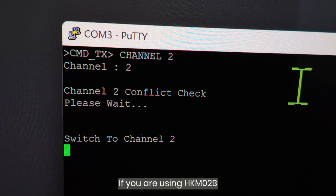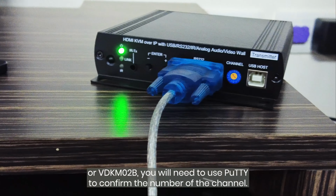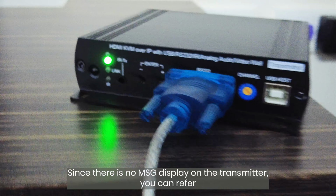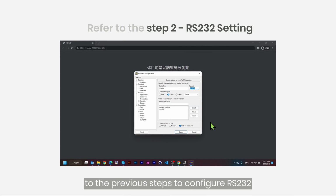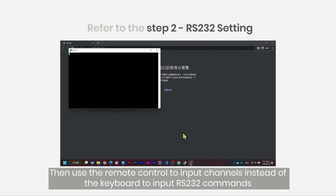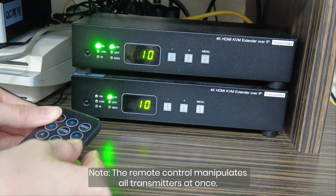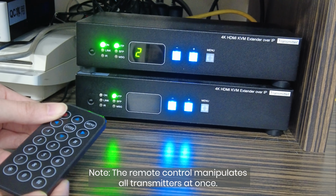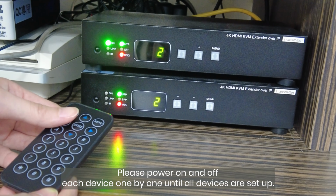If you are using HKM02B or VDKM02B, you will need to use PuTTY to confirm the number of the channel since there is no MSG display on the transmitter. You can refer to the previous steps to configure RS-232. Then use the remote control to input channels instead of the keyboard to input RS-232 commands. After remote control input, PuTTY will automatically display the input channel. Note, the remote control manipulates all transmitters at once. Please power on and off each device one by one until all devices are set up.